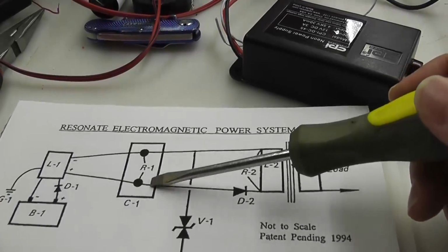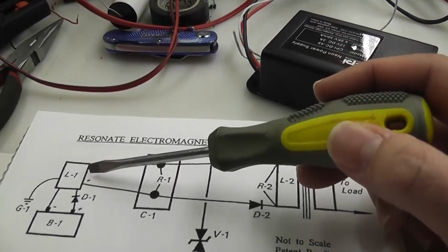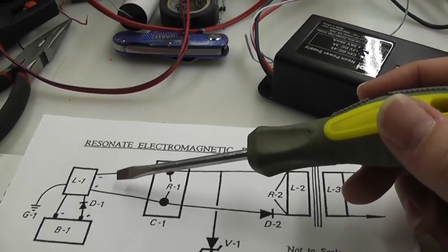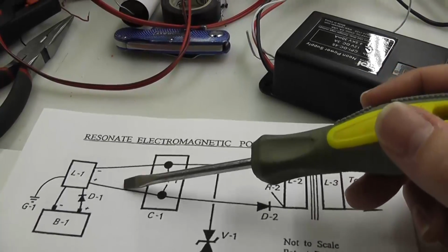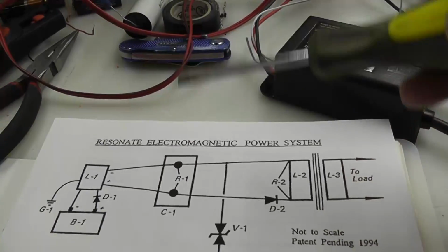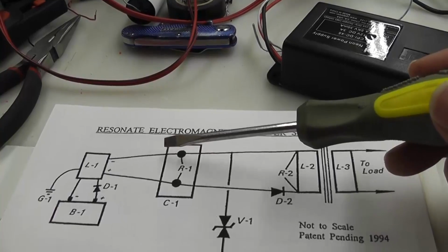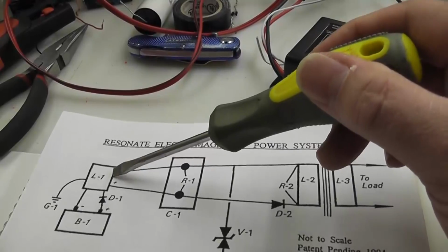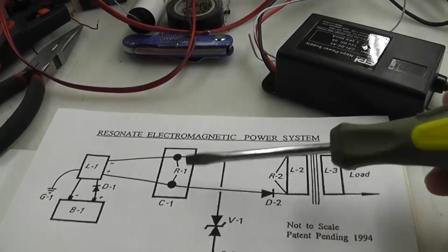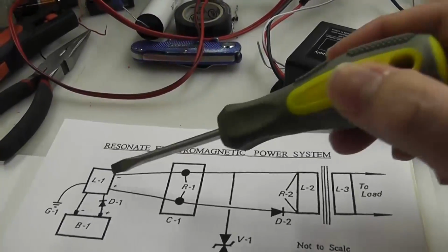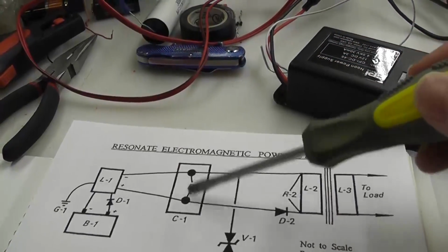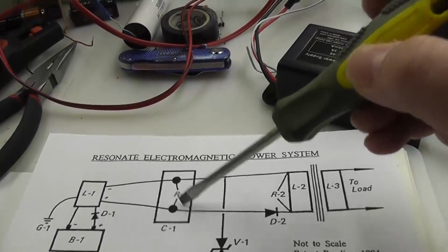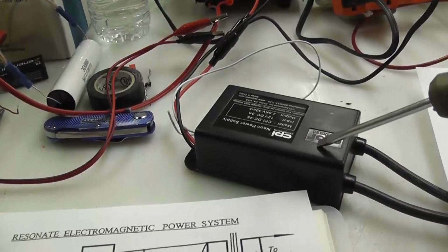Now the capacitor here, if you put a capacitor in parallel with this NST, it shorts it out and it turns off. So that does not work. Now let's assume Don is trying to find the resonance of this portion of the circuit, the coil inside here, the frequency, and the capacitor. If you put the proper capacitor in parallel here, never mind the resistor, this becomes an open. What happens in an open? Well, the NST shuts off because it senses an open. It doesn't work.